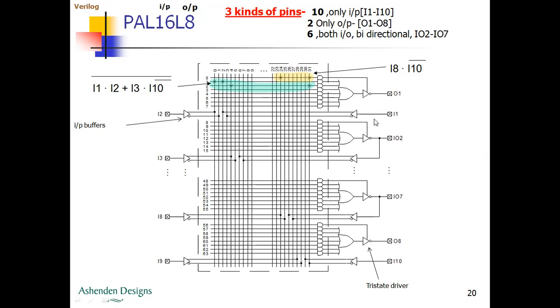Once the device is programmed, using these programmable instruments, it will blow off some of the fuses according to the function that is supposed to be implemented. So by keeping the fuses and blowing off the fuses, you can go for the programming of the PALs.